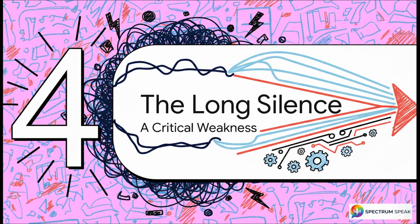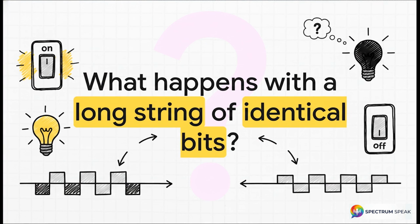So, NRZ's simplicity is its greatest strength, but it's also the source of its biggest weakness. There's a gotcha here, a hidden problem that can cause some major headaches in high-speed communication systems. So, what's the problem exactly? Well, it all comes down to what happens when you send a long, unbroken string of the same bit over and over. If that signal just stays flat at a constant voltage for too long, the device on the other end can literally lose track of time.